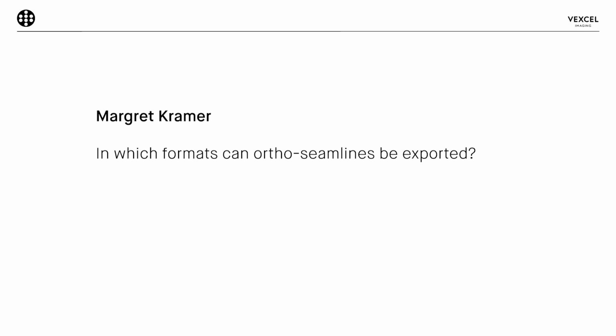These raster files have exactly the same resolution as the orthophoto. Every single pixel has in this mask one color, and this color represents one single input image. We then also export a legend to translate all the various color values to the input image numbers.